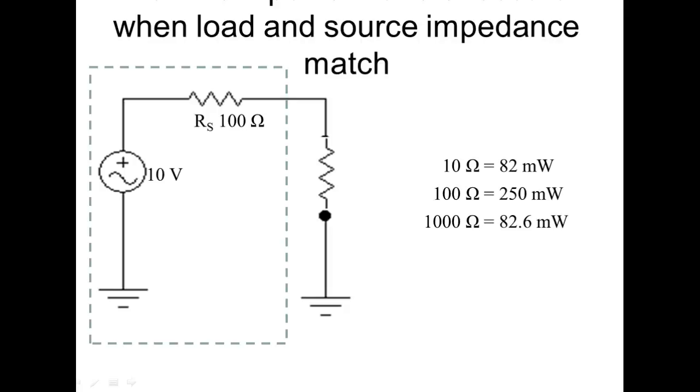Now this is not resistance, this is what? An impedance, which is AC, right? You understand that. If all the impedance matches in a communication system, then you get maximum power transfer from the transmitter to the what? To the receiver. So that's why when you hook up network, you have to use that standard twisted pair cable. You just can't run wires. It's a 100 ohm cable. It's a 100 ohm cable at 10 megahertz. Cat 5 cable, 100 ohm impedance.